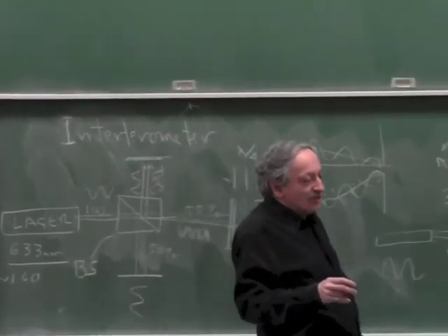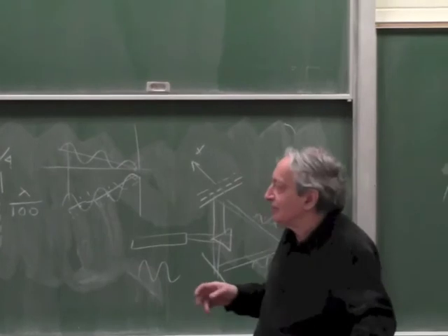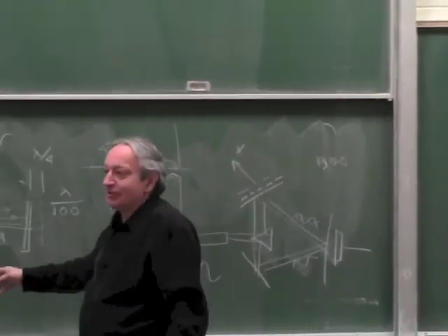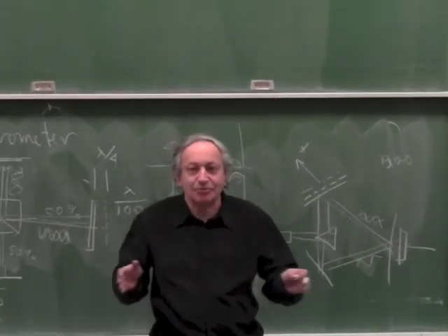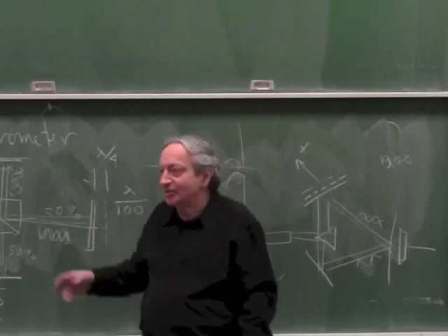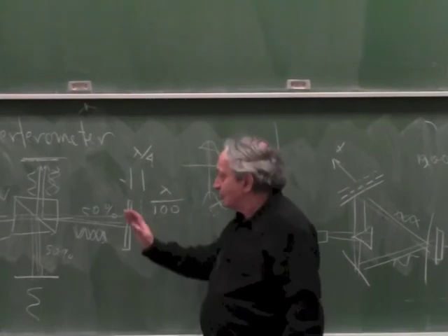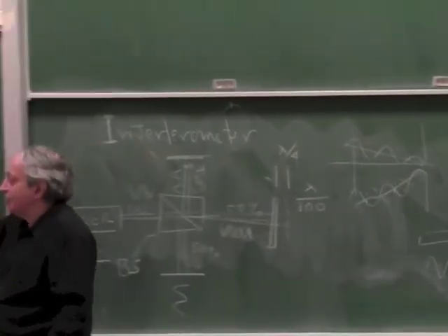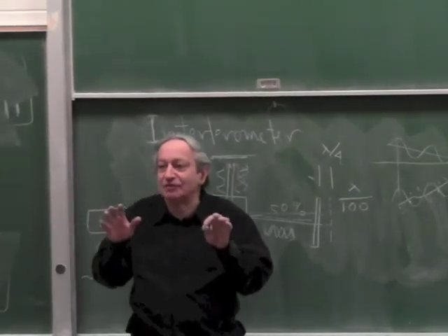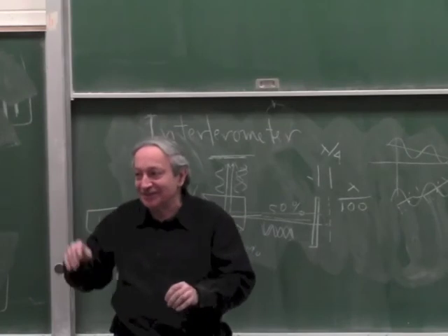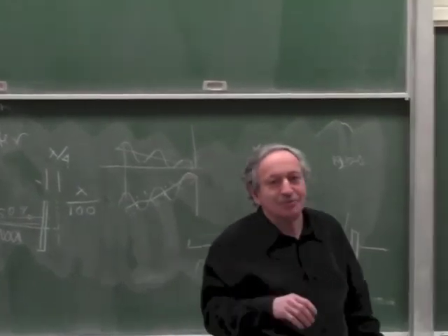Okay, so out of this whole idea of ether and all kinds of other ideas which turned out to be a mistake, something very good came out, which is an interferometer, which is the base sensor for very precise measurements, both linear and also rotation. You can build it so that it also measures tilt. Right? If this would tilt, then this whole band pattern will shift. And you can have two, so if they shift together, it's motion. If one shifts and the other shifts the other way, it's tilt.